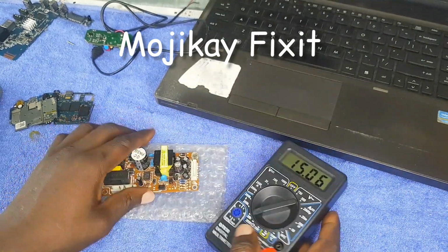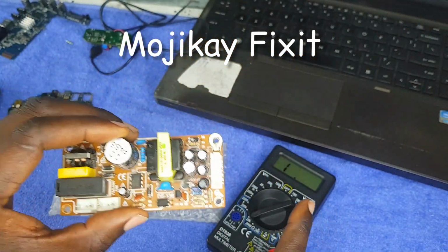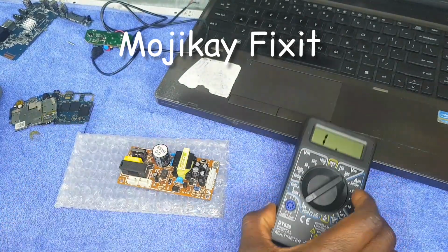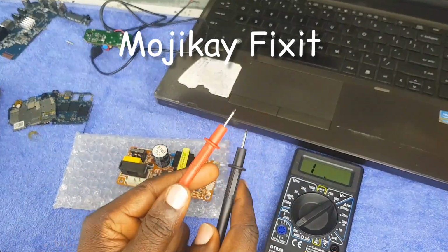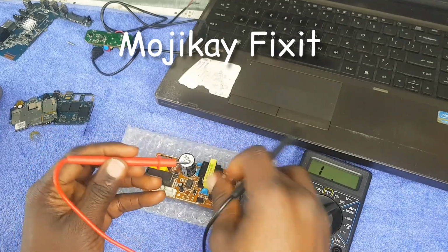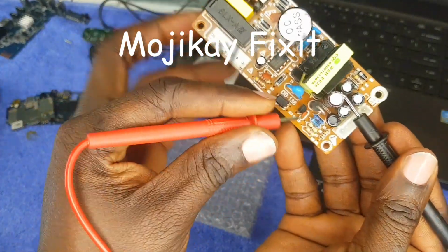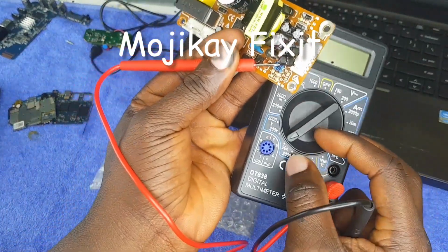Okay, now I'm going to start reading the resistor on this PCB, then we'll go over to the mobile PCB. All right, let's take readings on these resistors. So reading resistor, it doesn't matter where your probes touch. Your probes can touch any part of the resistor, any end of the resistor. So taking this resistor reading, I've put my dialer right on 20k.